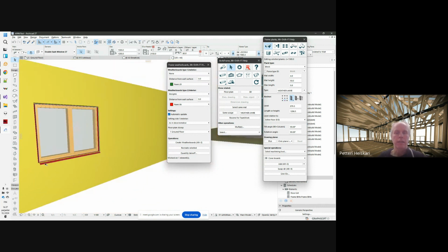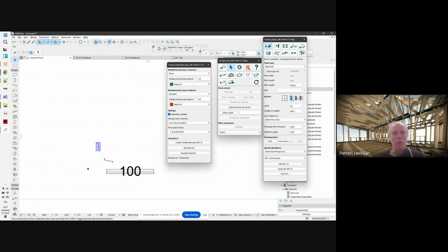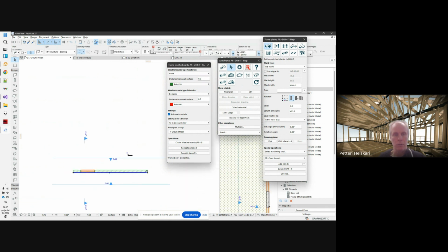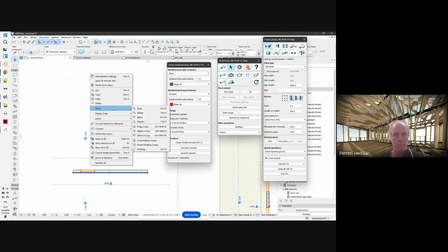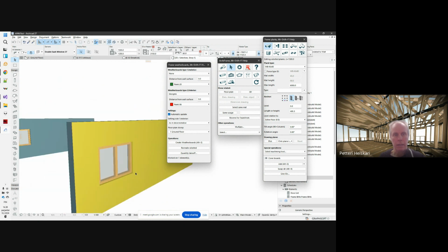And to test your definition, you will need to test it for walls with different geometry. So to do that, I'll mirror a copy of this one. We mirror with a horizontal line, and then let's see these in 3D. And let's apply the rules to all these windows. Just in case, I'll create that for every place.